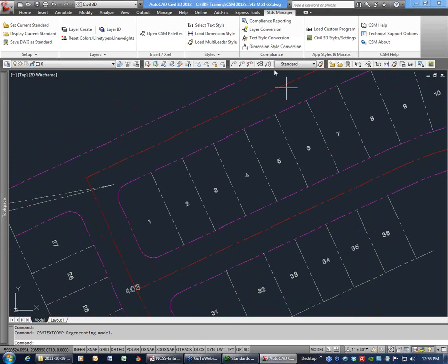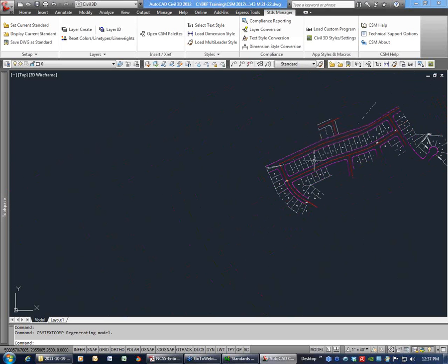And it's nice to be able to, there's some other search tools in there. Dimension style conversion is not going to help you at all because you don't have any dimension styles, but it's very, very similar. Okay. All right, so back to Jocelyn's question here. Can the status of existing blocks be converted to annotated without redefining the block? No, it cannot. It has to be redefined. Good question.